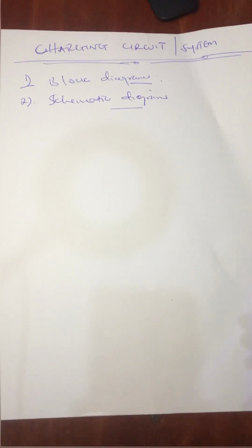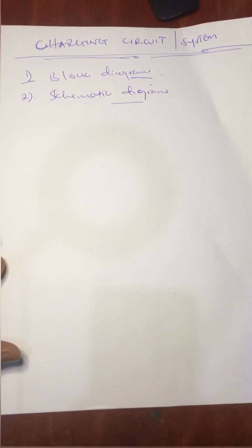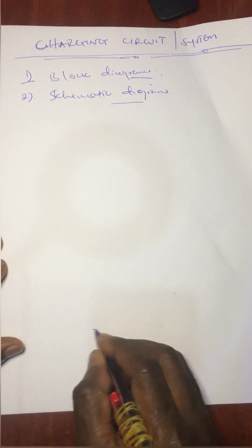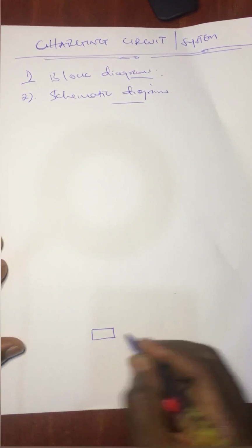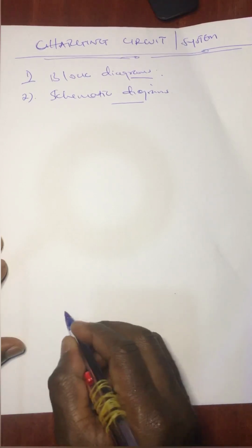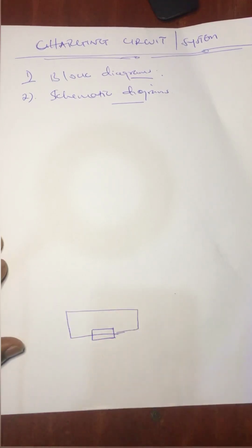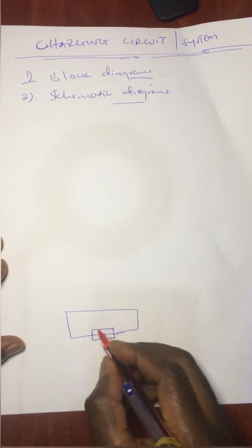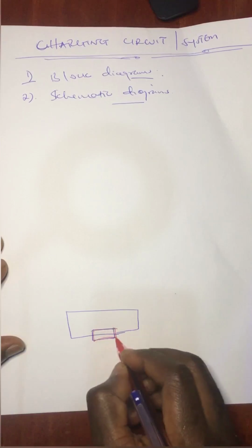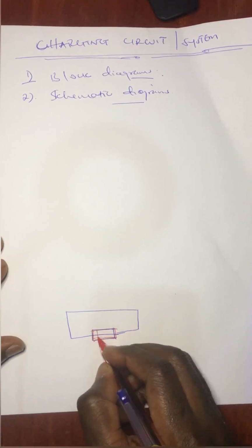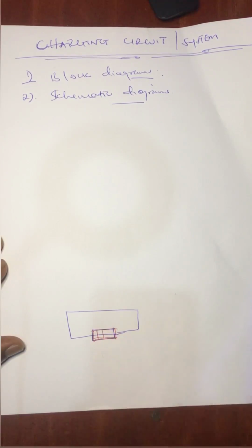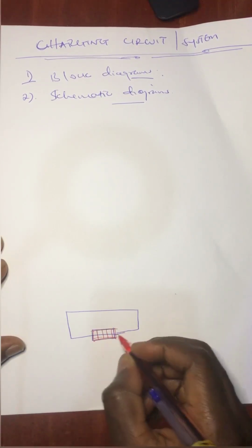So let's get started. When we talk about the charging system, mostly people will think of the charging port, right? Because that is the external view of this system. To begin with, the charging system has a charging port, and the charging port is attached to the underboard, or what we can call a charging board. So this is the charging board, and on the charging board we have the charging port, which has basically 5 terminals.